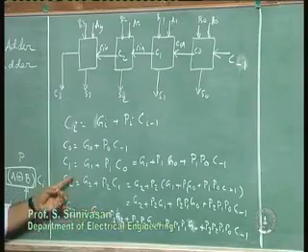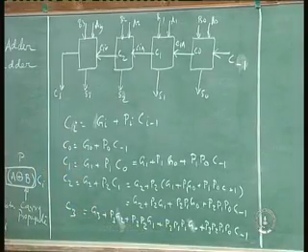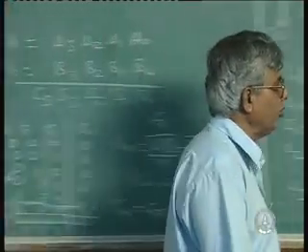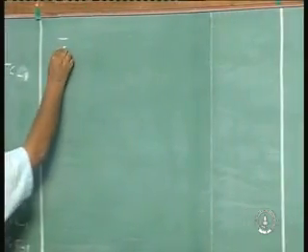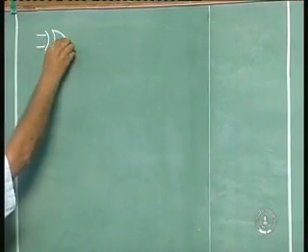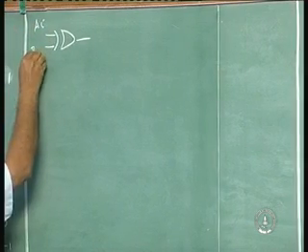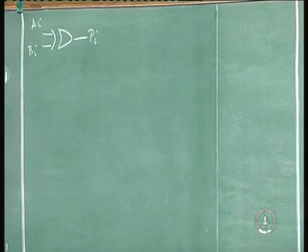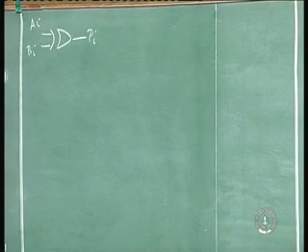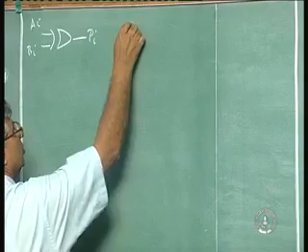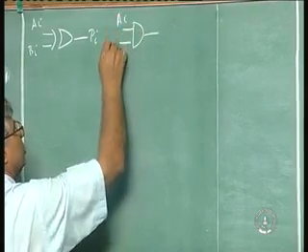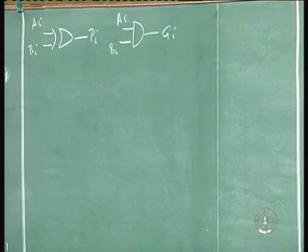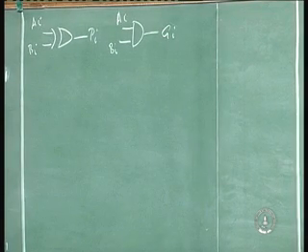Now what is this logic? All these G's and P's are known, because G is nothing but an AND combination, P is nothing but an exclusive OR combination. So I can have my P's and G's generated like this. Ai, Bi gives me Pi. I have 4 such gates for P0, P1, P2, P3. I have G's, Ai, Bi, Gi, 4 such AND gates.